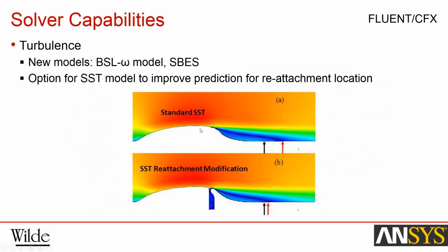As you can see, if you check the reattachment box in CFX, the numerics are much better, such that CFD and experiment tie up better together. Obviously, in version 15, you could have got CFD to match up with experiment if you had a very fine resolution mesh here, but then that's going to take longer to solve. If you use the checkbox method and a decent mesh, you're going to get much closer for a lot less hassle.